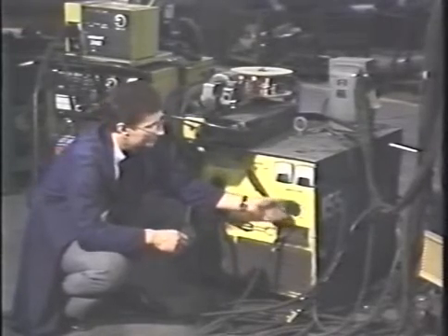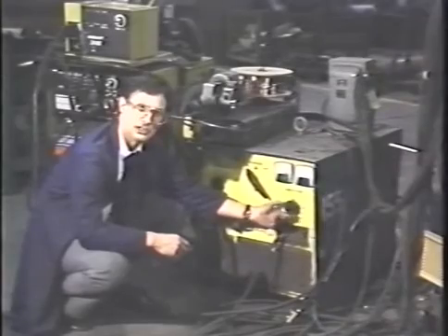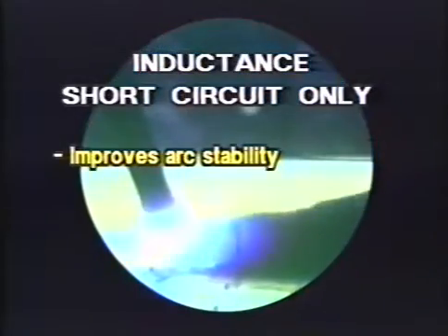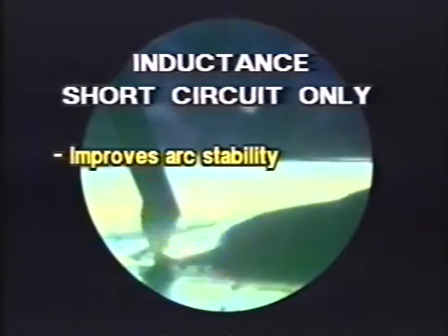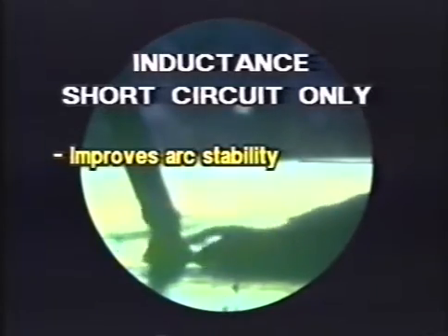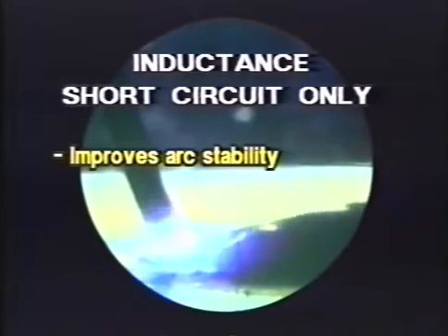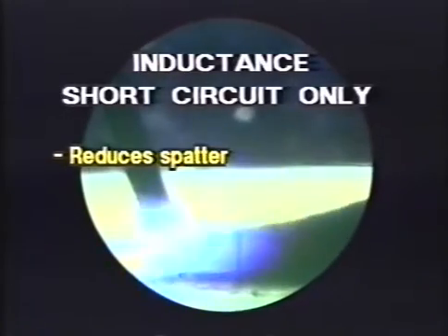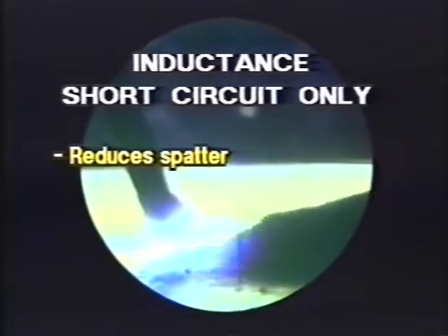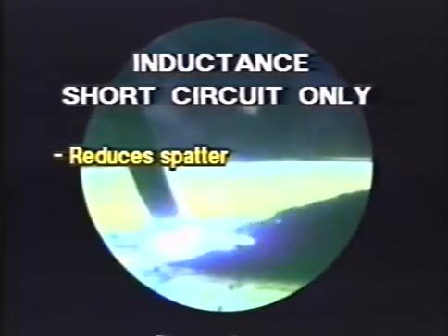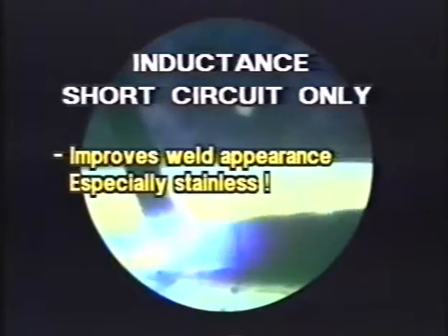Again, some machines have inductance. What is inductance? Inductance is beneficial, again, in short circuit applications. It kind of slows the current down each time a short circuit takes place, so we don't have this instantaneous response and surge and explosion. In other words, it's really beneficial for cutting down on spatter, and because the arc is on time a little bit longer, the short circuit welds may be a little bit more fluid and therefore look a little bit better.